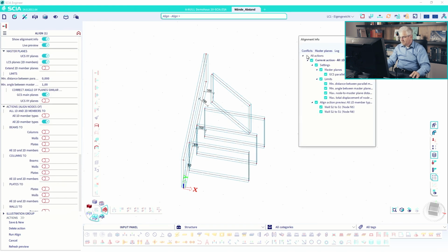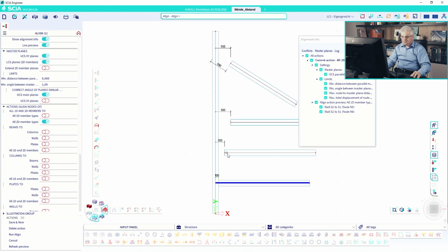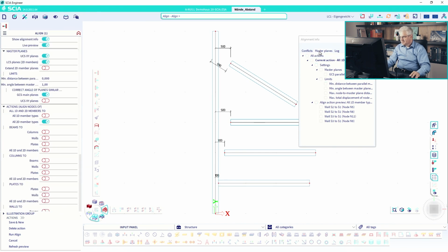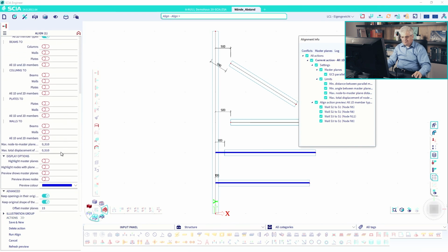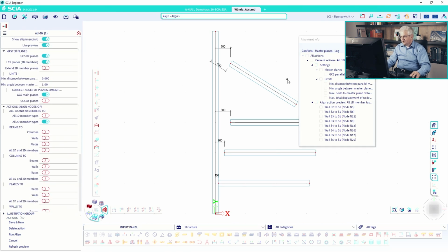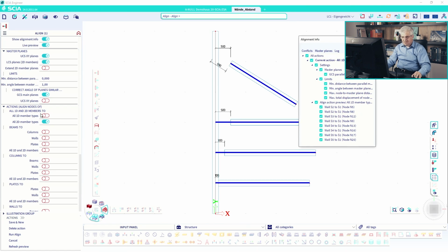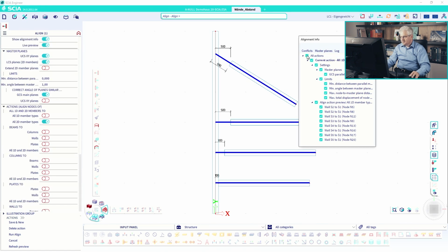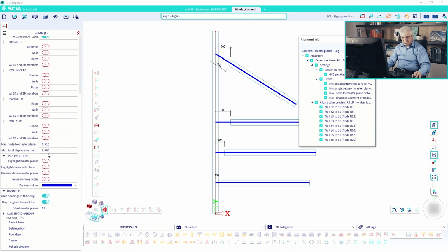and check the preview. So you see this one will be moved and this one not, because this is more than 20 centimeters. So we can try 0.31 and check it. Okay. 0.51 for example. It's okay, but this one cannot be moved. We have to extend also this distance, for example, to 0.6, and then everything will be moved. So these are these two distances explained.